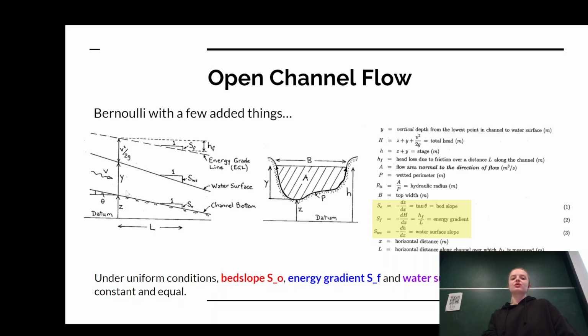We're also going to introduce three different lines. The bottom line is the channel bottom, so if we have a sloping channel, we have to take that into account. Then we have the water surface, indicated by our SWS down here, the water surface slope.